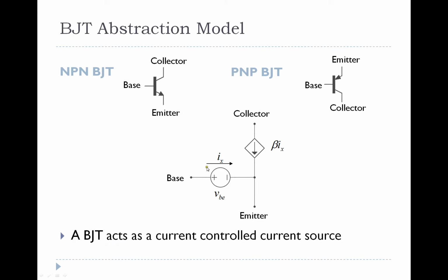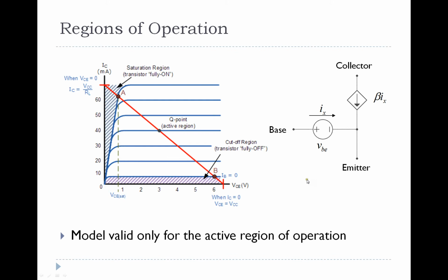So we're going to try to force a current in this direction to increase the current between the collector and the emitter. Thereby, if we can get a large amount of current injected between the base and the emitter, then this is going to act like a wire because it's going to allow a lot of current to pass through. If we get no current to pass through, this is going to act like an open circuit. So in a way, we can make this act like a switch.